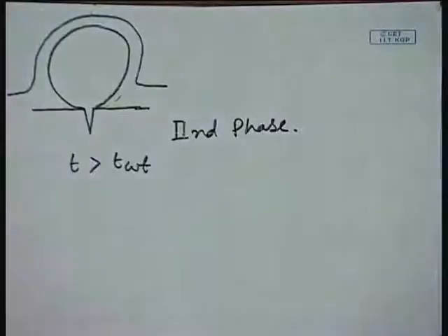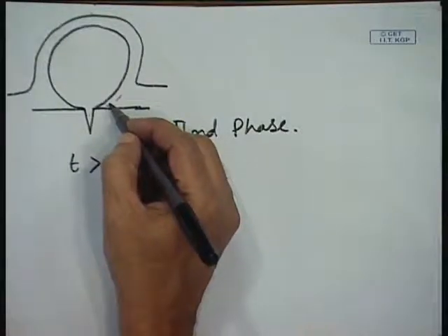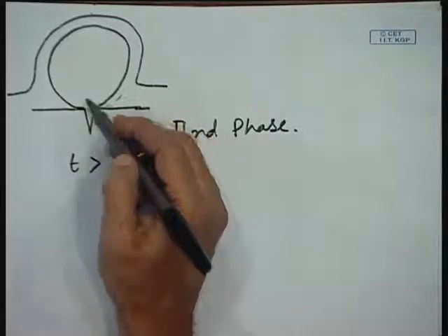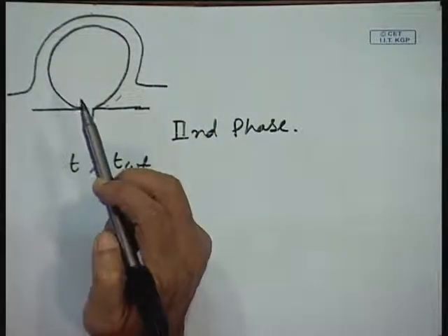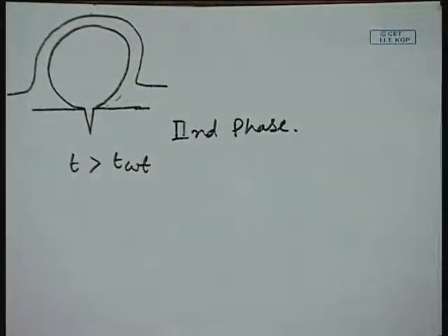Okay. And another thing you can see, I have represented the bubble as a spherical bubble. Why have I represented the bubble as spherical? Because now heat transfer from the lower side has really reduced. Now more or less uniform heat transfer is there all over the periphery. So, the bubble has become some sort of a spherical bubble. But one thing you have to remember, these are all ideal discussions based on some ideal model. In actual practice you will get something in between. Okay. So, this has become the spherical bubble.